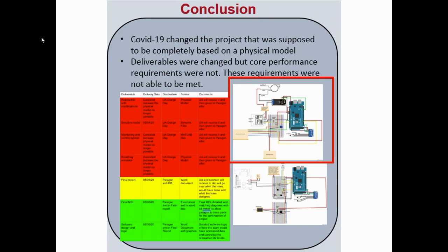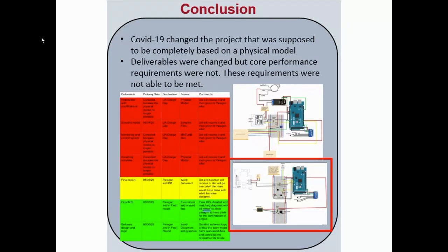The second wiring diagram illustrates integration of all the components that are necessary for controlling the solenoid valve used for oxygen addition into the breathing loop. External power supplies will need to be incorporated to satisfy the operating voltage of both the CO2 sensor and the absolute pressure sensor. Additionally, a 9-volt power supply will need to be integrated into the system to allow for proper actuation of the solenoid valve. Furthermore, a 16-bit analog to digital converter was added for the oxygen sensors in order to increase the precision of the readings obtained from the sensors.